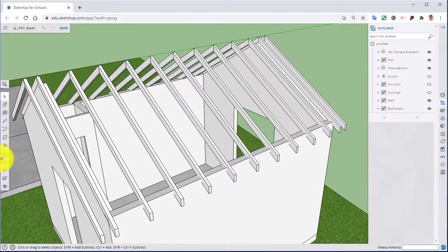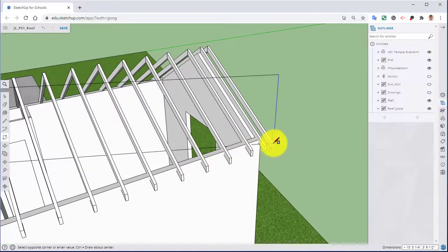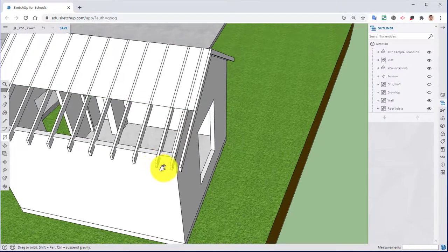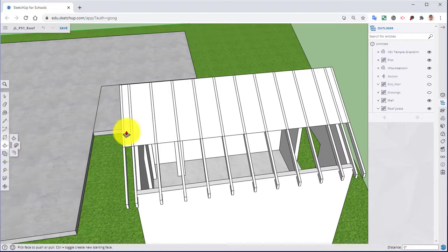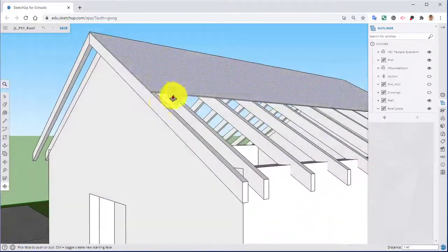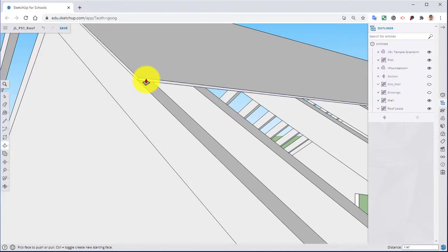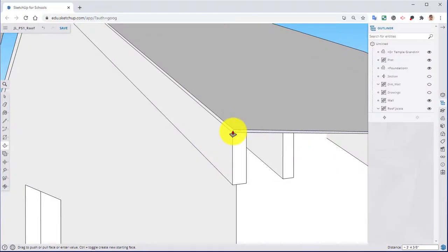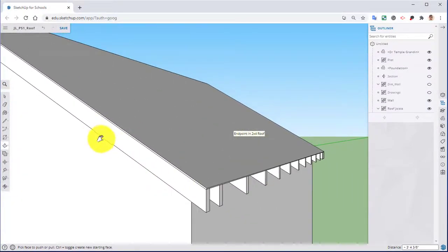Next, we're going to lay our sheet of plywood on top. So go in. It may not work if you do it at the very end. So come in here towards the middle, create our rectangle, take our push-pull tool, pull this up. We're going to do 0.25. Take our push-pull, click on the very edge, and drag this down to the end right there.